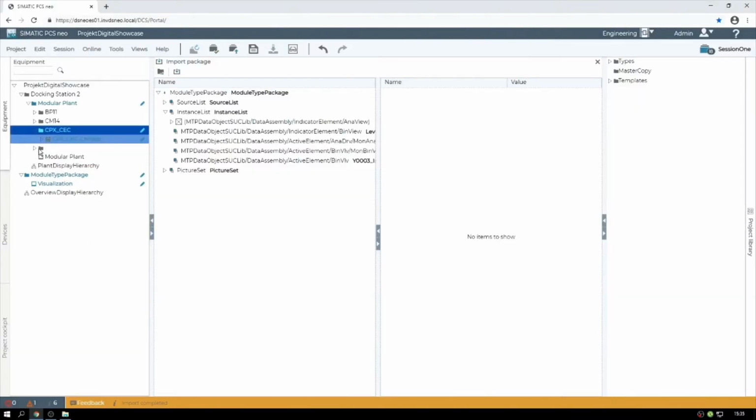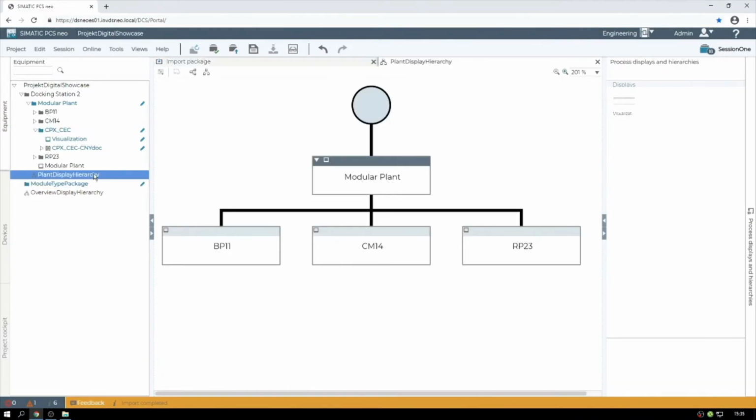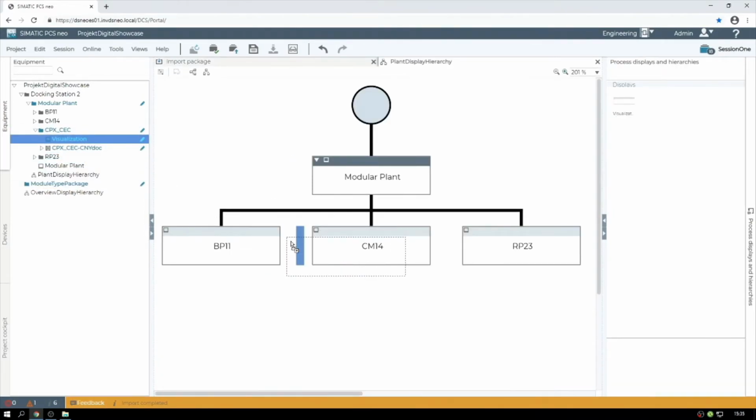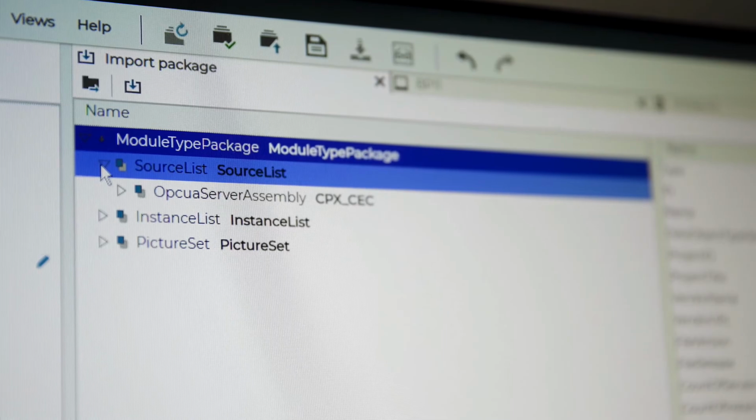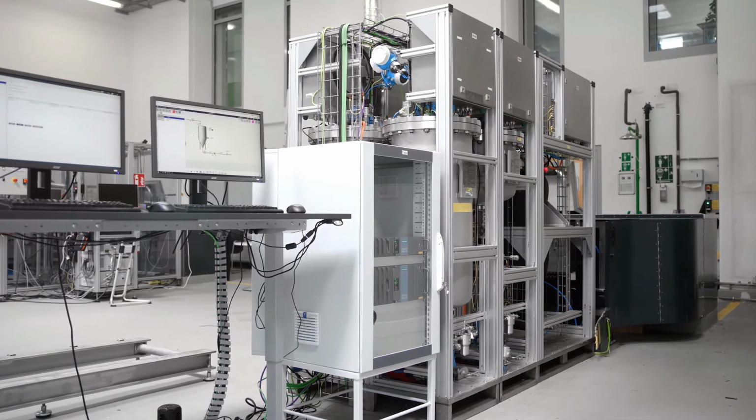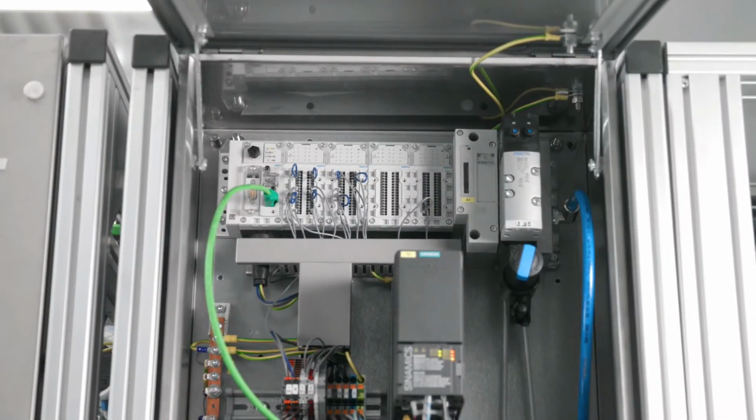The MTP consists of several parts like HMI integration and services. The Festo MTP could already provide those parts. Unfortunately, the orchestration layer was not able to support the service function, but we could demonstrate how the HMI import works. If we want to use MTP today, we need some important functions like safety, which are still under development in the standardization process, so we probably have to wait for this first.